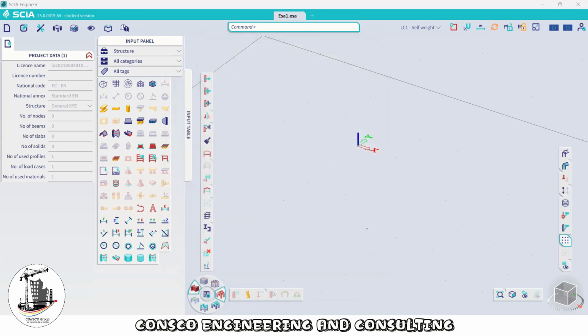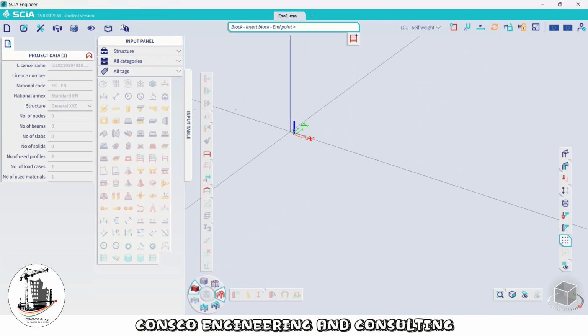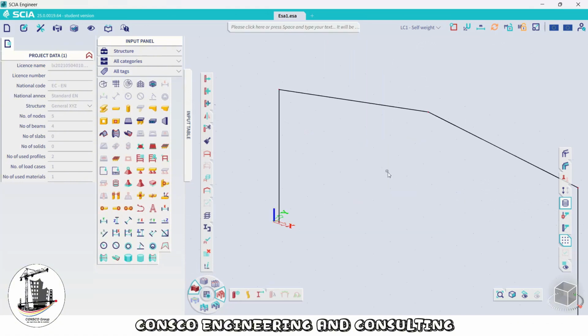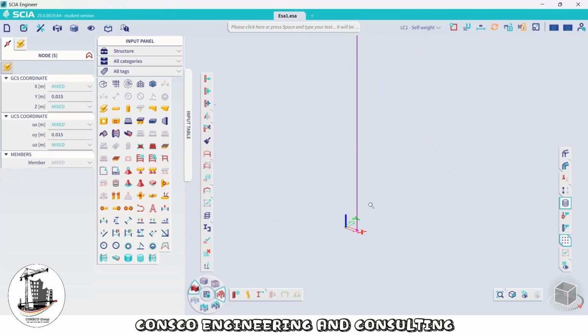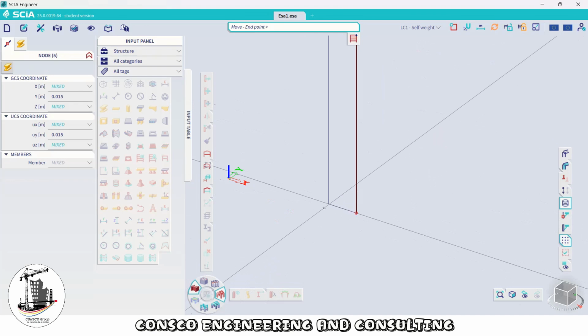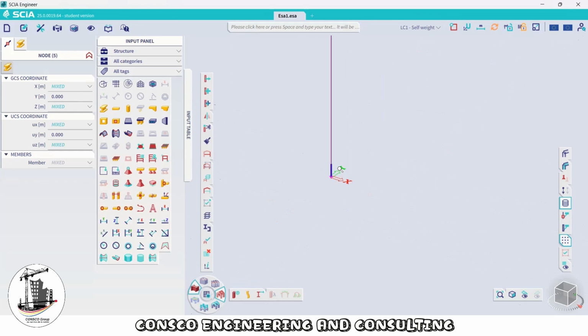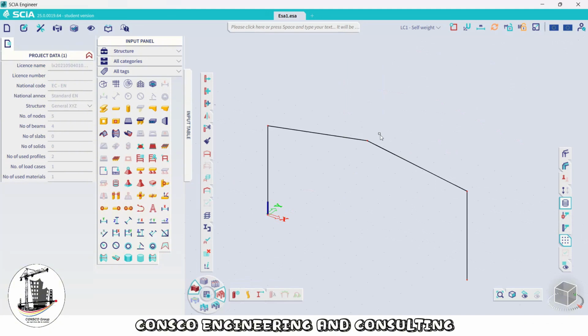When you click OK, now we just need to define the position. You can put it anywhere and later you can still adjust. Let me put it first here. This is the frame, and when I finish I can just do Control A to select everything, and then Control X so that I can move it, select the point and move it to 0 0. Now it's at the origin of the coordinate axis. That's how we define our first frame.